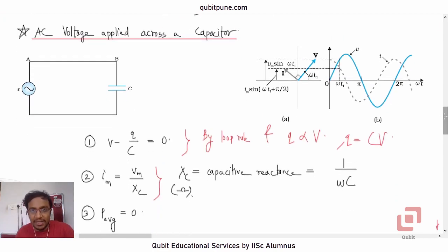What about the phasor diagram here? Remember CIVIL. So now we need to consider the first three letters, right? First three letters. Current I comes first, V comes later. So current will lead the voltage. So phi will be pi by 2, positive pi by 2 rather.